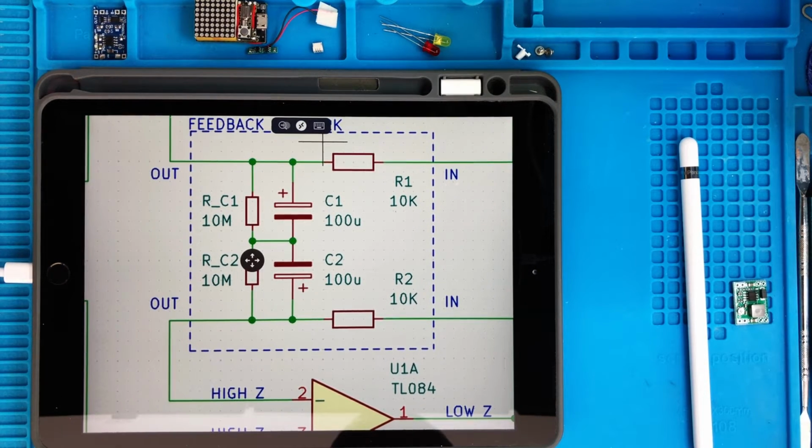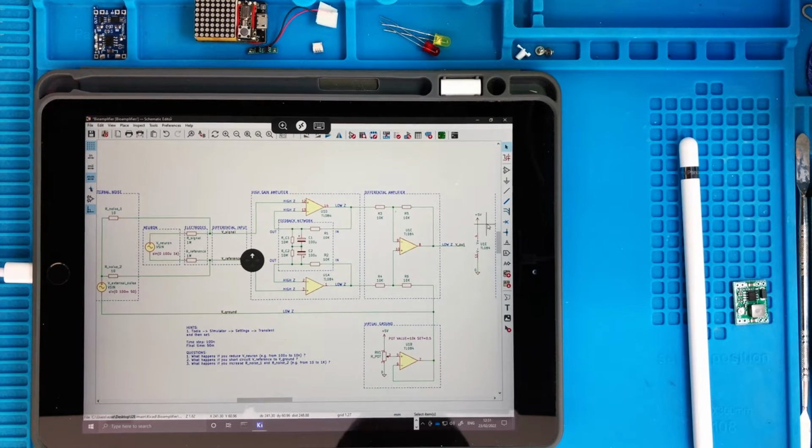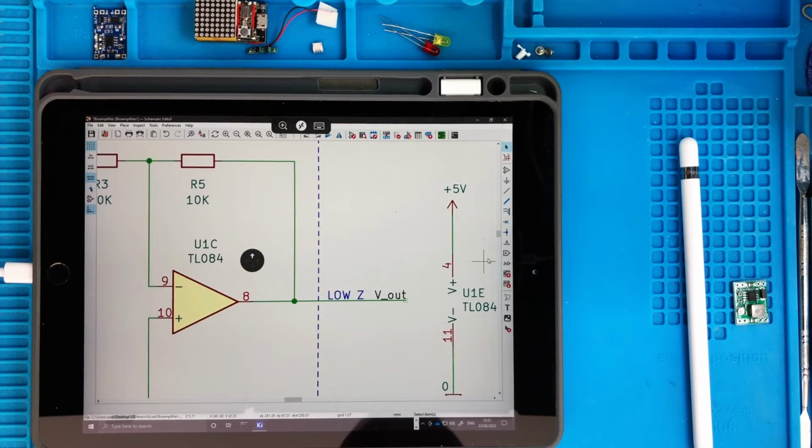Other things that you might need as generic information: you see in this quadruple amplifier there is a fifth part which is seen as a component in the CAD, which are the two pins for the power supply of the chip. We have to remember that an amplifier is something that amplifies a signal, but the power of this amplification is taken from the battery, which is connected to it. And so we have to provide power to the microchip.